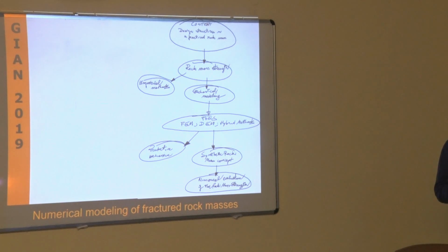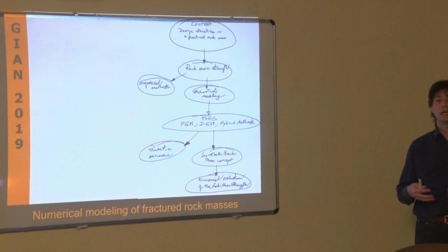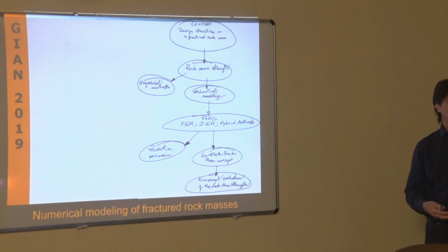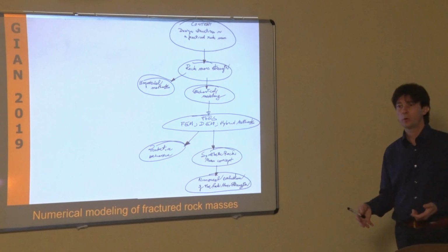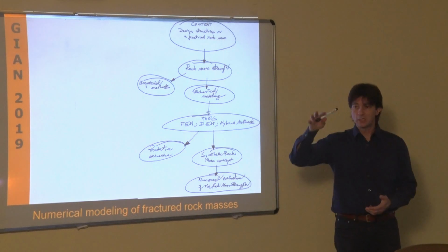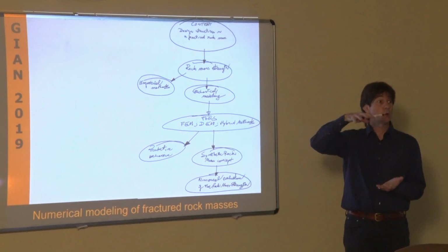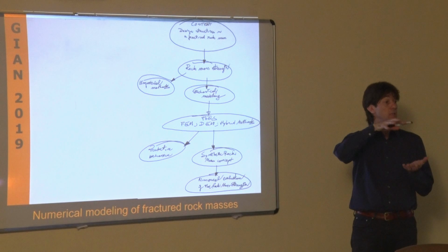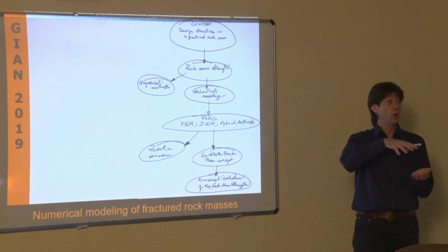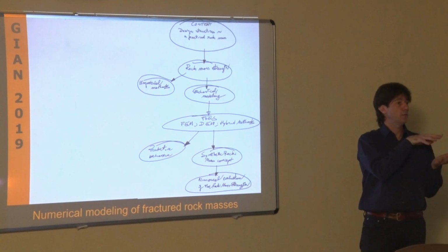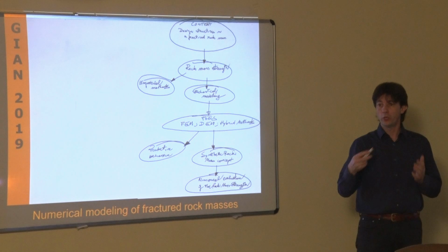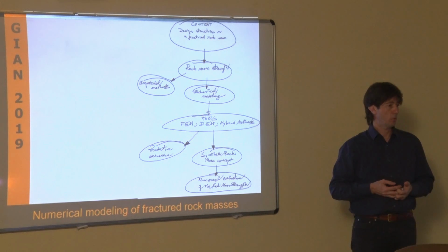One thing is that you need to always be aware that prediction gives you one single result, but you always have an uncertainty on your inputs. So you need to see what if my input is a little bit different. What if instead of using one single value, I use a range? How sensitive is that parameter, so how much care do I need to investigate that particular cohesion for the rock.